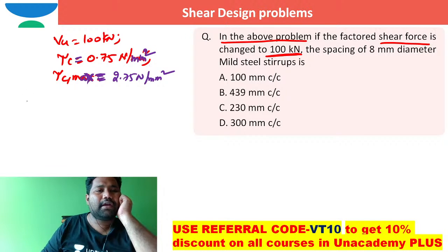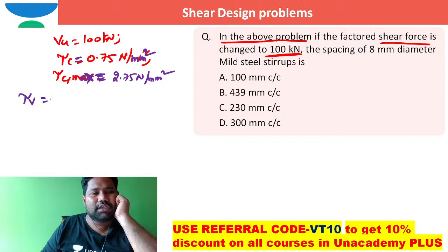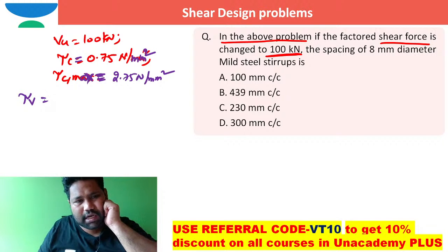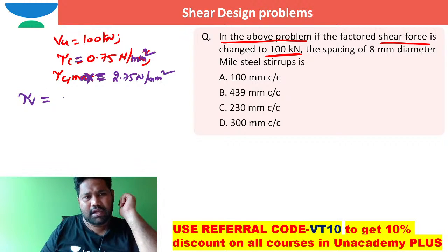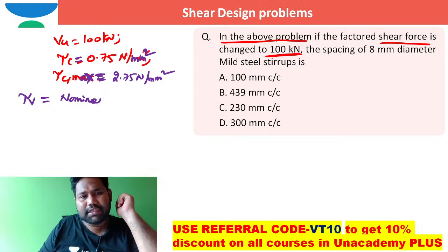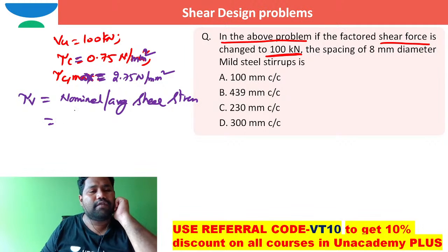Now I need to compare between tau v and tau c. Tau v is the nominal shear stress, nominal or average shear stress. If it is that one, directly we can write Vu by bd.